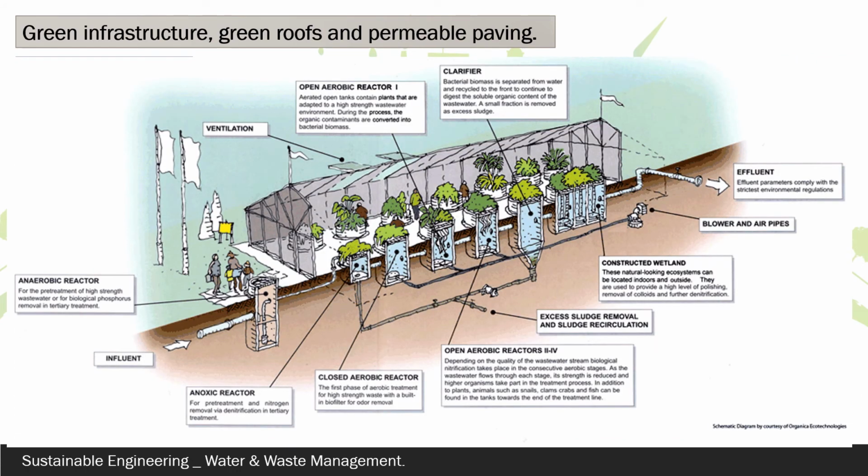These treatment areas though can be easily configured depending on the environment you're in. As you can see on the screen here, this is a number of different tanks, one after the other, all providing a slightly different use within the system. The key to these is to allow sunlight into the tanks to allow plantation to aerate the waters within them. Matter within the tanks would drop to the bottom, feeding the plants for long periods and allowing small microclimates to build up, dealing with the waste. The water would then pass from tank to tank before being moved off into a reed bed or water system nearby.